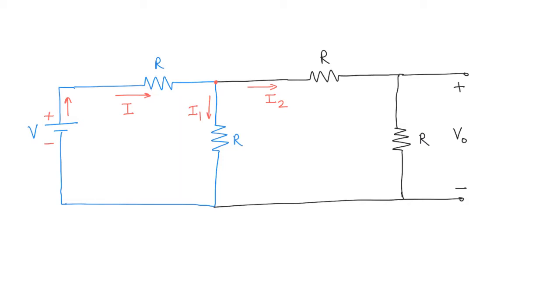Now all this current I2 is also going to flow through this resistance, because the current here is going to be zero, because this is an open circuit and you can't have current. Imagine charge is flowing here, and if there is no path for the charge to go out of this point, if there is a current flowing, then charge will be accumulated here.